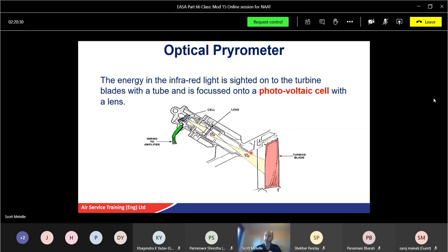Well, on the initial ones, there was a lot of carbon buildup on the outside of these, and we'd have to take them out every so many hours and do what was called a clean and cal. Actually clean the pyrometer lens with a special cloth, then we put it into a special radiation source and actually induce a pretend radiation wavelength, and we would calibrate the pyrometer to make sure it was within limits.